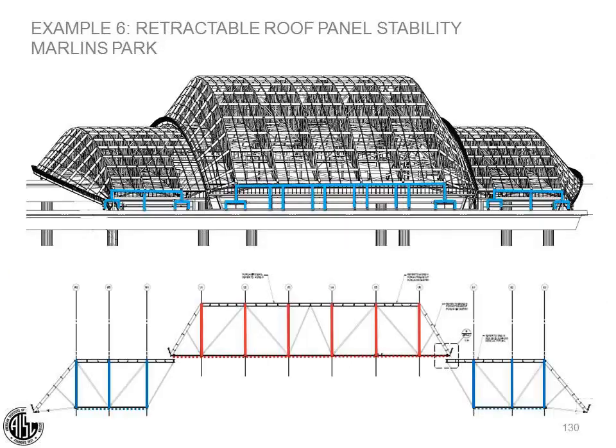And this is a section looking in the transverse direction. In the lower diagram, all the gravity, stability, and lateral resistance is provided by the horizontal bracing trusses at the truss bottom chords and braces that extend up to the upper chords to brace the top chords. In the top diagram, the moment frames that stabilize the roof panels in the left-right direction are highlighted in blue. We use flexible moment frames in each end, as you can see highlighted in blue here.